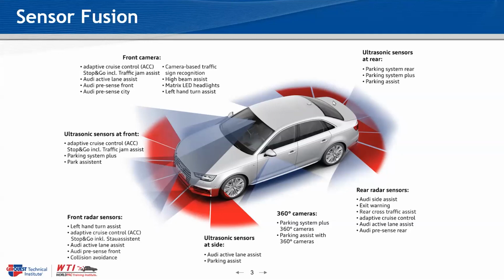Well, it goes right back to what we were talking about, specifically the sensor fusion. That overall resolution is due to multiple systems looking in the same direction of travel and measuring some of the same things. I would think that if one or two of those systems is identifying one direction of travel or one distance of an object, and another one is off, that is where our DTCs would most likely come from. Of course, some radars and front-facing cameras have other things. If we've pre-calibrated them and then there's been an adjustment and now something's off, it's going to be looking to other systems as well, some that aren't even on this list.